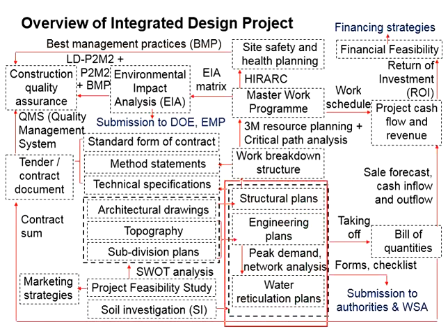The contents in those plans are itemized, and the quantities of the materials are estimated in order to work out the bills of quantities. Then the bills of quantities will be a part of the tender document, inviting the contractors to bid and participate in the project.